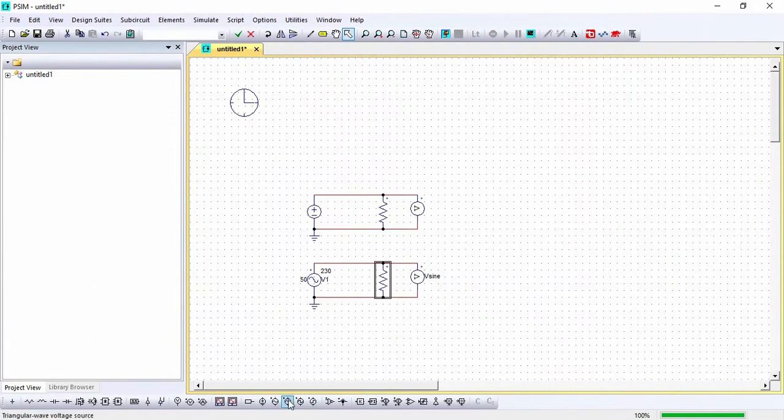In our case, the third wave is triangular. Different types of functions can be run in the triangular and square waveforms. We'll see them one by one. Here I am taking one triangular source with a single resistor and a voltmeter parallel to it. Now as we are all aware of the connection, it is very simple, so I am connecting it in a rapid manner. We need to provide one ground here.